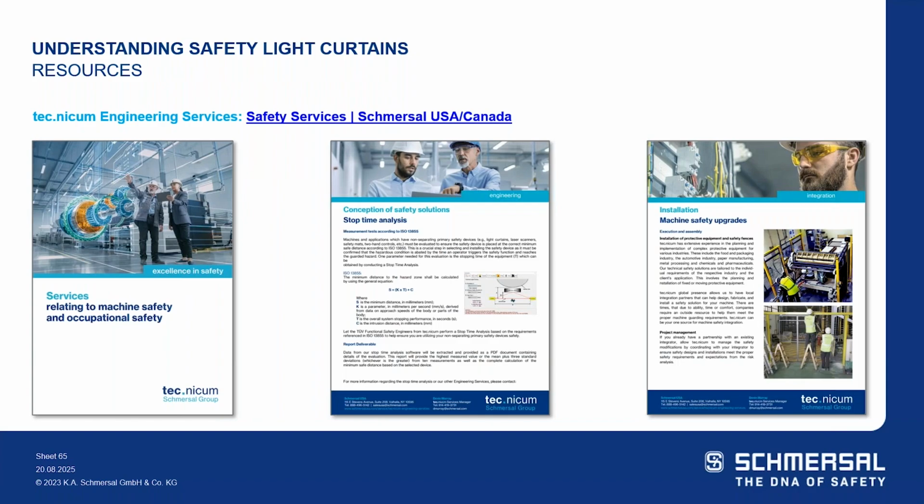We've got a complete brochure. With our engineering portion, we can provide expertise for every life cycle phase of machine and plant construction involved in the design of new machinery and process, and the retrofitting of safety functions during the modernization of older machines. We can perform the stop time measurements to calculate the safety distances for those guarding systems and carry out the validation of the safety functions and provide the necessary documentation.